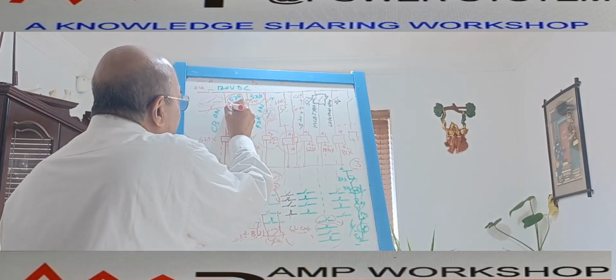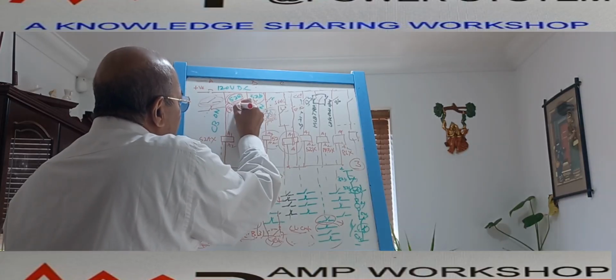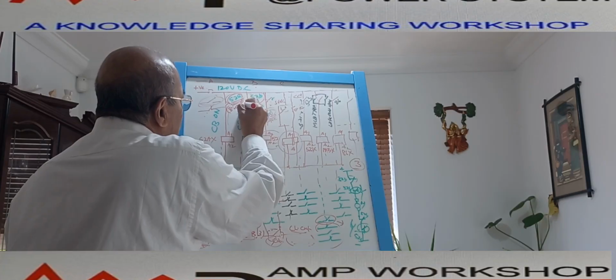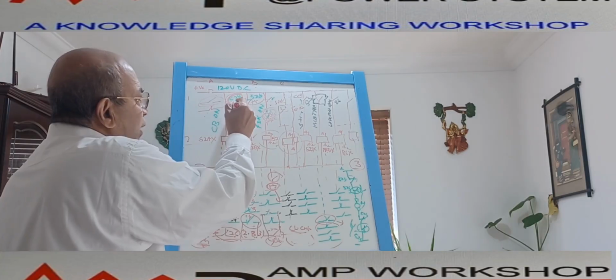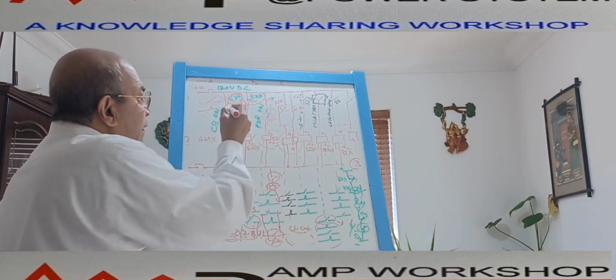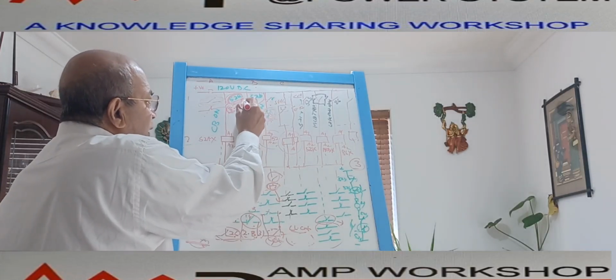In that case, here we write it this way: suppose page number 8, row C and column 2. In this way we mention this so that it is understood in which drawing this 52A is physically located: page number 8 of this drawing set, row C and column 2.